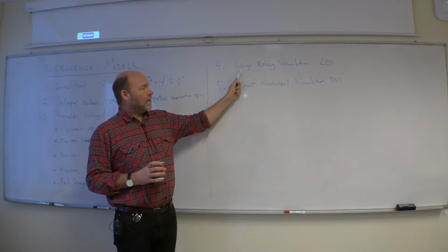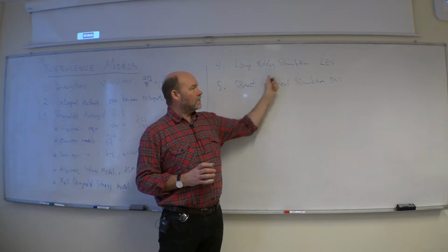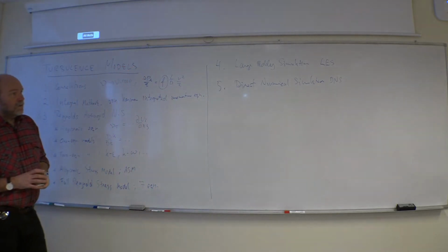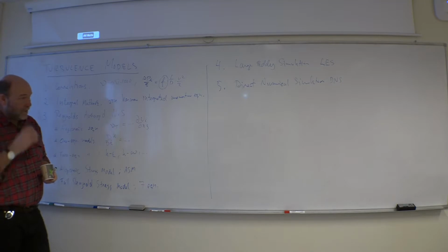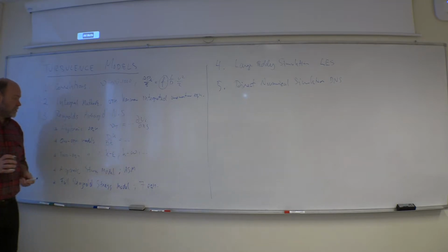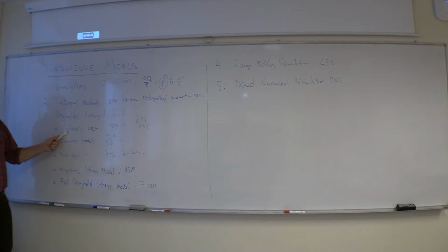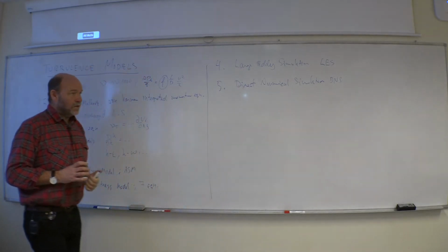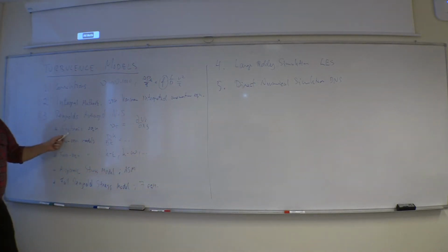It covers the large scales, the large vorticities, the large turbulence motion. But inside the cells, you use a very simple model. They have tried using more advanced turbulence models inside one single mesh, but it's actually not worth the effort. So a very simple model inside your cells.